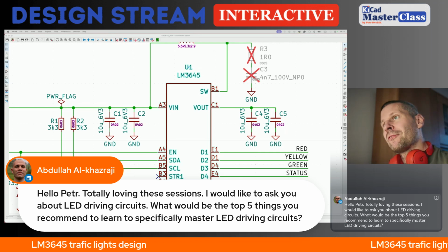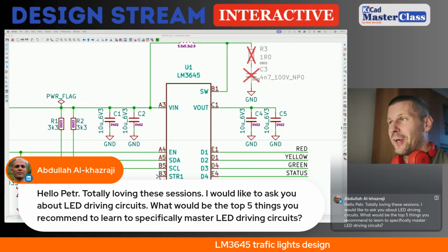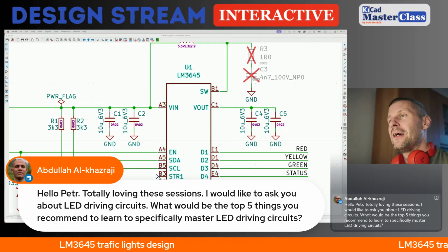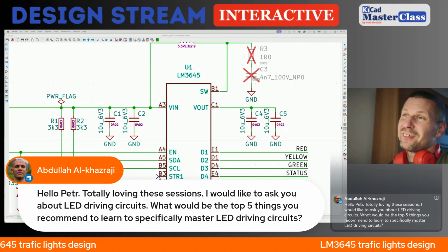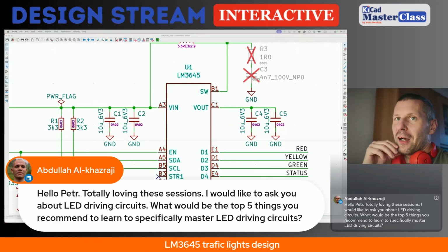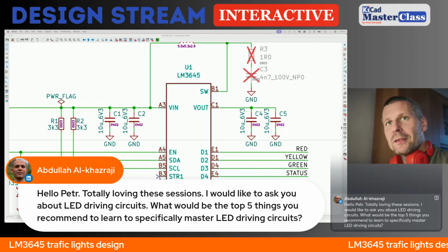Then you have to be careful about forward voltage when setting the current, when using the shunt resistor for setting currents. So you have to calculate rather carefully the LED forward current. There are characteristics in the datasheet. So start with the datasheet.